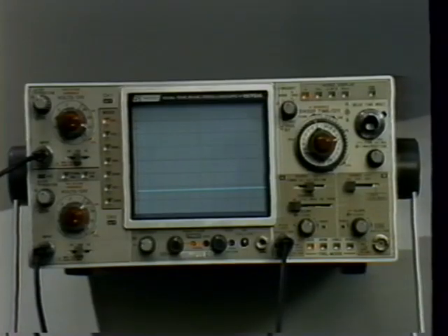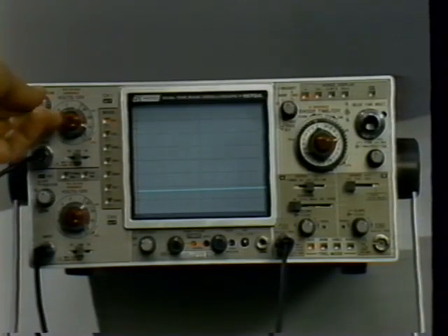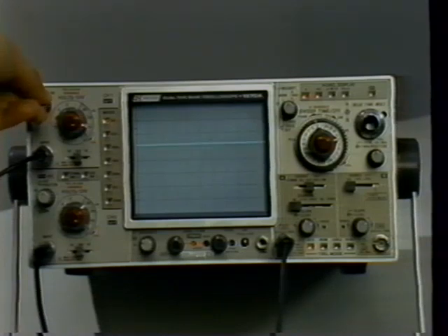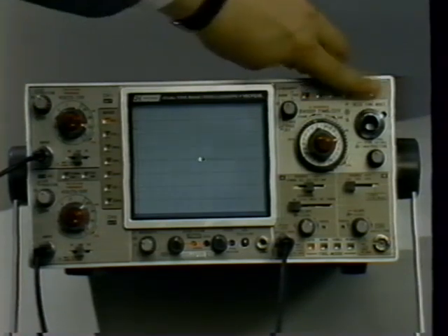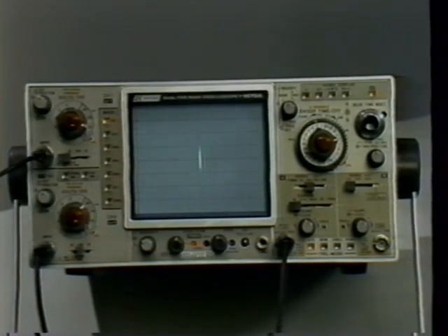The vertical position control provides a variable DC bias to the amplifier. This bias alters the output to the driver and ultimately changes the position where the signal appears. Without horizontal motion, the vertical section would produce a straight vertical line representing the signal's voltage swing.